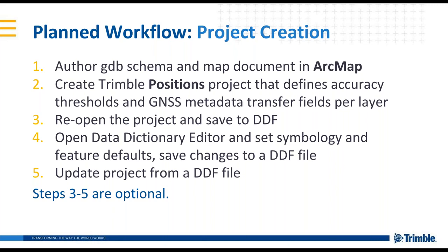You would then reopen the project and save it out to a DDF, okay? So there's a screen for this. And you can then take that DDF right out to the field and start doing work in it. If you're not interested in checking out existing data, if you want to just do new data collection, you also have the option of opening up that DDF in Data Dictionary Editor, setting symbology, setting feature defaults, making other changes that are specific to TerraSync logging options, things like that, and then saving those changes to the DDF file.